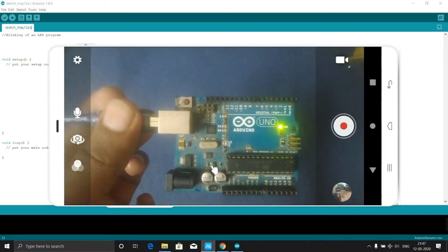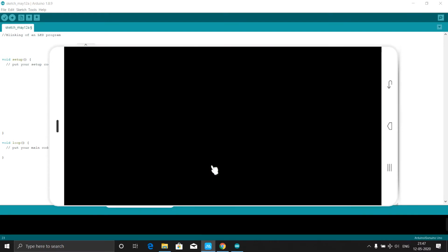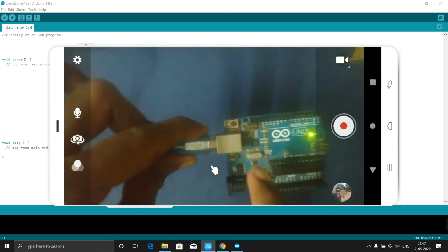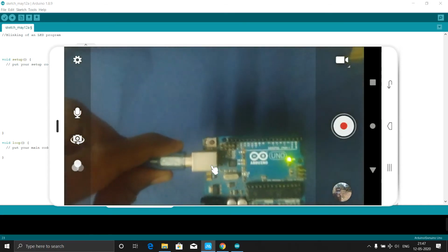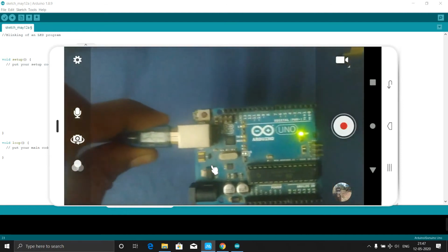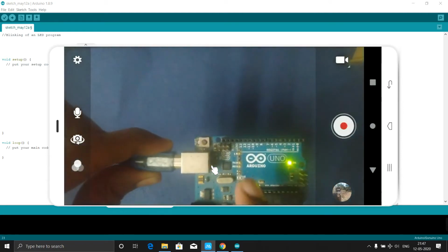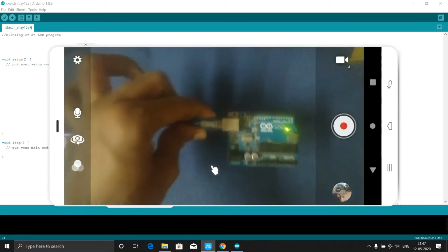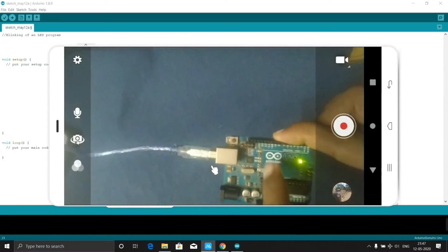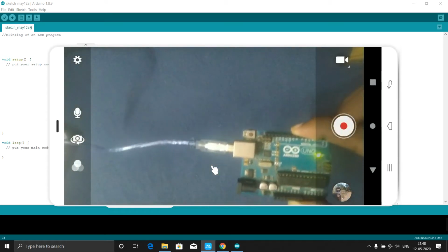And for this, first of all, we need to tell this Arduino, hey Arduino, make this 13th pin as output. I need to connect some bulb or I need to use this LED. So make this 13th number pin as output. For that, if we tell the Arduino once that you should make this 13th pin as output, the Arduino will understand.